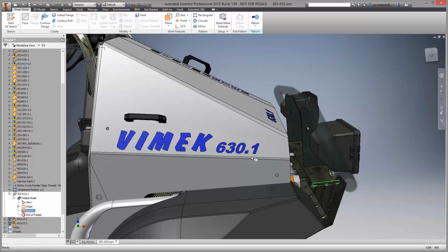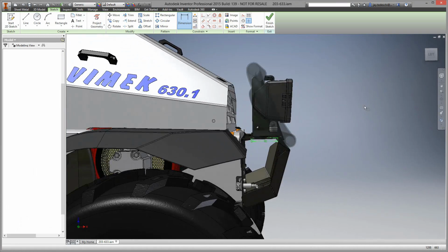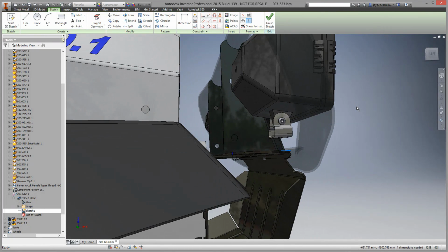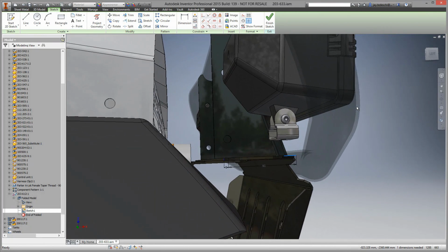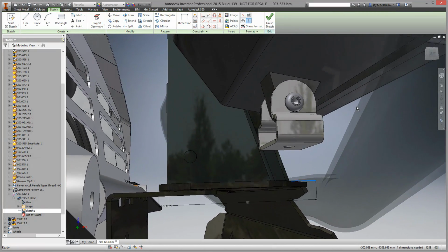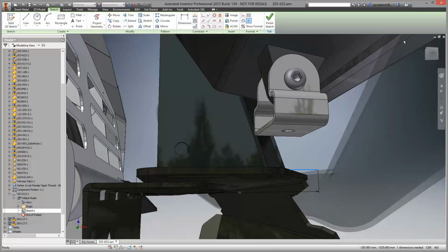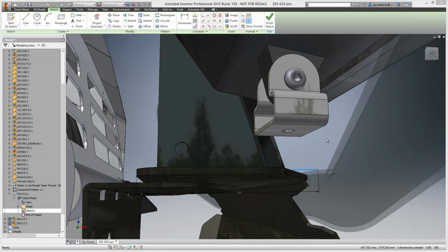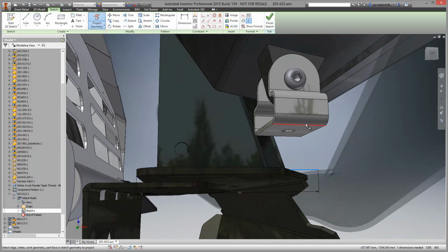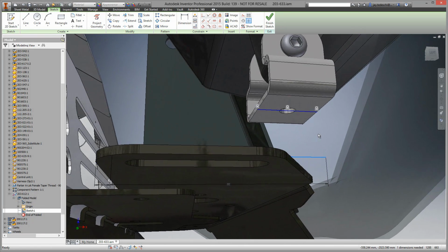I have a piece of reference geometry here, previously created. I don't want to be redundant here. I just want to make sure that we show you the new constraint settings and the changes that have been made to the sketching constraint environment, because they're very, very powerful additions. So we'll start by projecting some geometry. We'll pick this edge, and you'll note that immediately we can see the display of the constraint. It's projected geometry, so the geometry itself is locked.